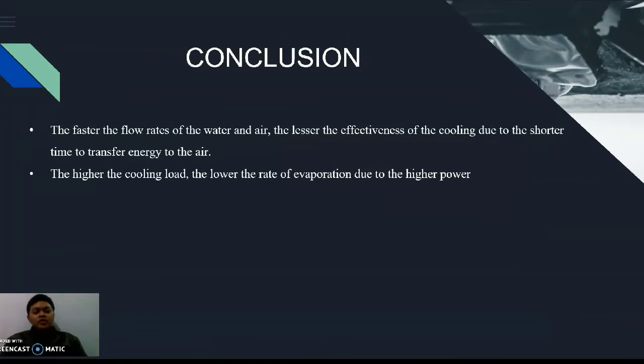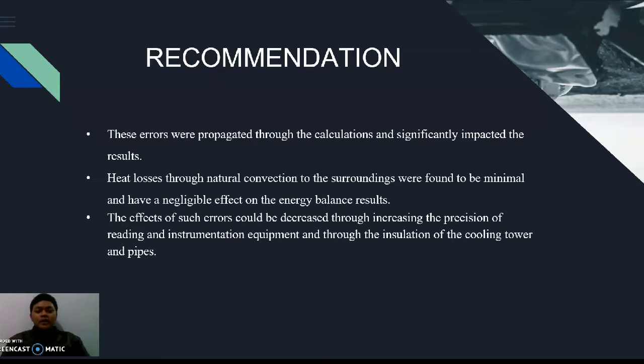Next, we proceed to the conclusion of the lab. First, the faster the flow rates of the water and air, the lesser the effectiveness of the cooling, due to the shorter time to transfer energy to the air. Second, the higher the cooling load, the lower the rate of evaporation due to the higher power.